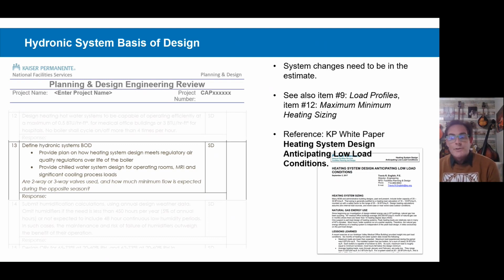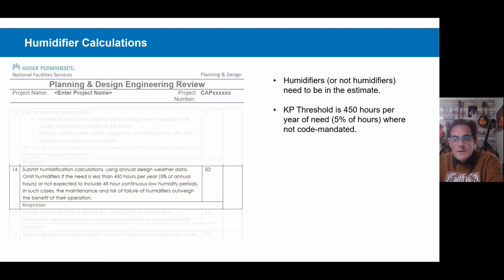This is chilled water. This is condenser water. We need to look at minimum flow rates at equipment, any kind of variable primary flow configuration. Those minimum flows will kill your design intent. And for primary-secondary flow conditions, is it okay for the flow in the secondary loop to be less than the flow in the primary loop, as is often the case when you look at minimum flow rates of equipment, right? So all that has to be worked out in schematic design. The answers to those questions need to be worked out.